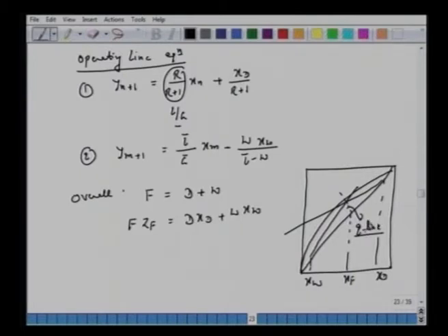Okay, so now in our case, when there is no reboiler and we have direct steam and we have the bottom product L bar, which is nothing but our product W. This is G bar here, which is nothing but the steam flow rate. How can we modify this approach and do the same calculation we were doing earlier?